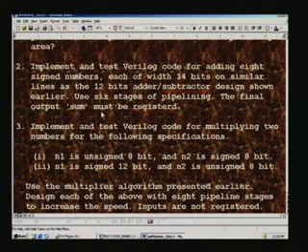Each of width 14 bits, on similar lines as the 12 bit adder subtractor design shown earlier. Use 6 stages of pipelining. The only difference is that in the earlier 12 bit addition we had only 5 stages of pipelining. The final result, the sum, came only as an assign statement, and we did not register it. But in this case, the final sum will have to be registered. That means after the 5th one, you have to add one more clock after the assign statement for the sum. So you add one more register as the 6th register, and that completes this sum. This is the one which we are going to use.